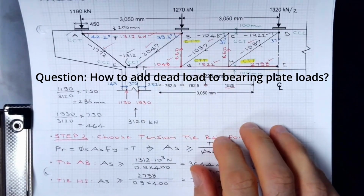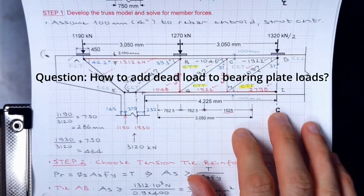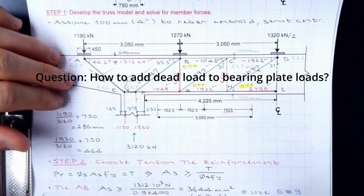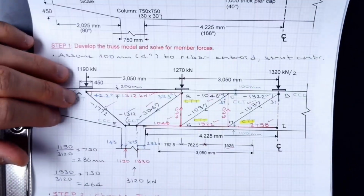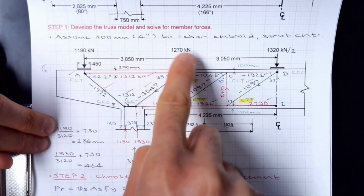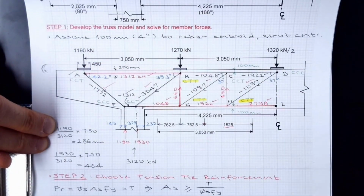Yeah, that's another good question. Dead load is really up to you as the designer, and I'm working with multiple companies and they have certain approaches. When you do a structural analysis, even in the sectional method, you have to put that dead load onto the system. So nothing different. Whatever approach you use for your sectional analysis for putting the dead load, the thing is that you want to account for these factored loads. So it has to consider dead plus live. If you have impact contribution, you have to include those.